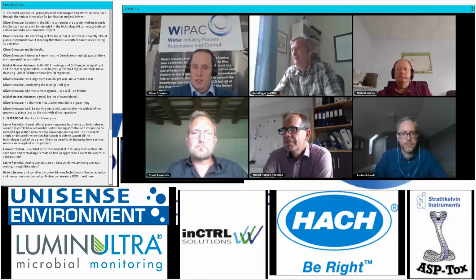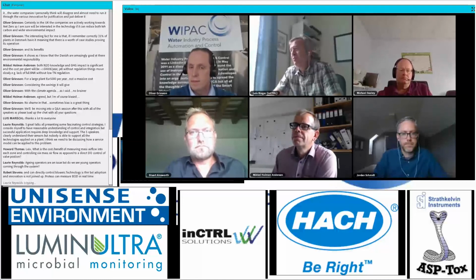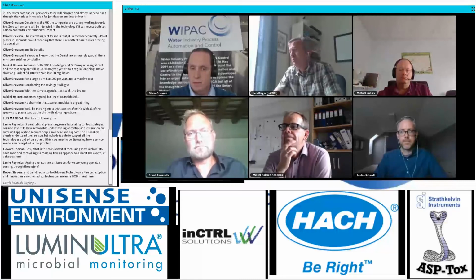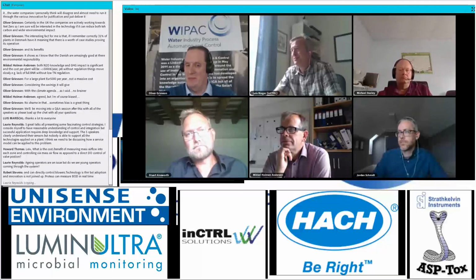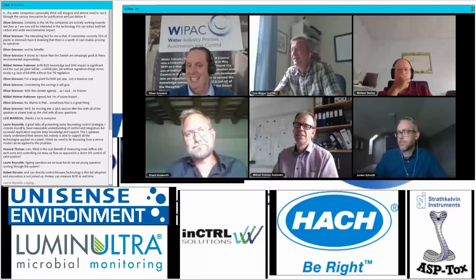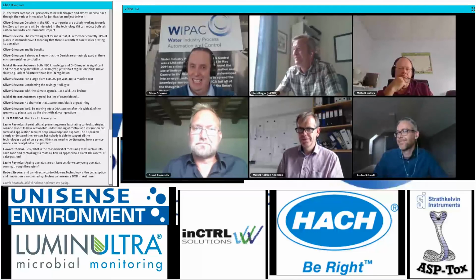Mainly if you use ceramic diffusers, and you go lower than a certain limit, then you may destroy them. And airflow for mixing, same thing. There is a certain limit you need to maintain. Little anecdote: as a PhD student, I questioned everything, and I actually turned it down too much, and I thought airflow for mixing limits were just for somebody not daring enough. They had concrete fouling and had to repaint the whole tank after. So it's important. I learned my lesson.